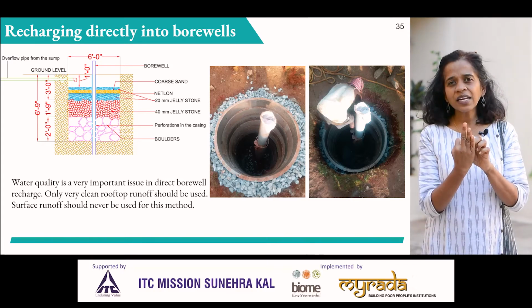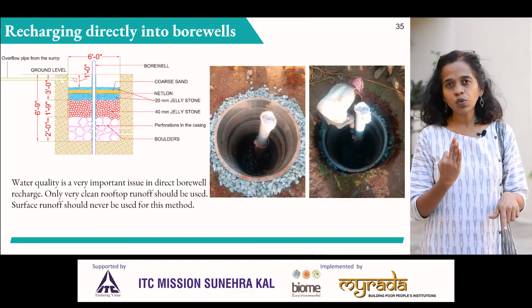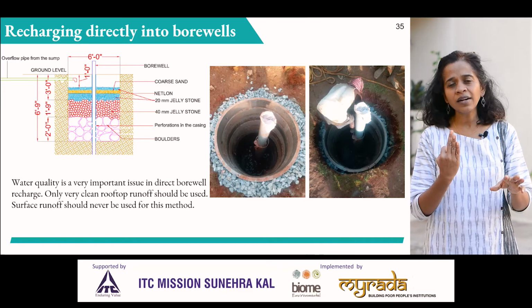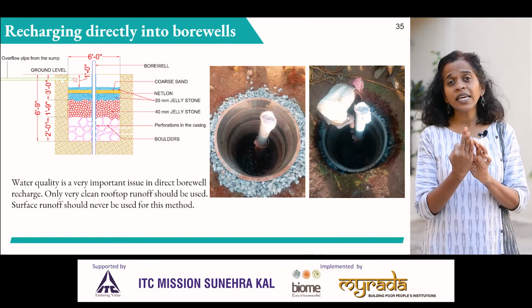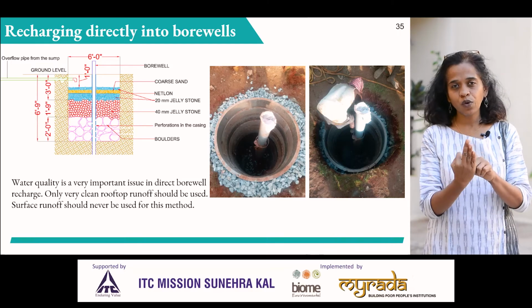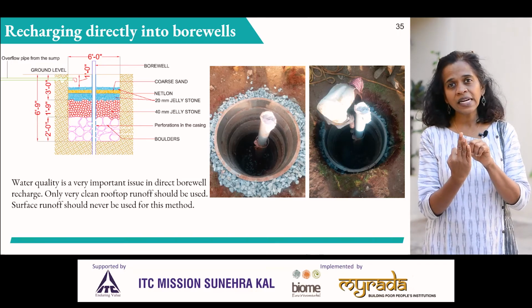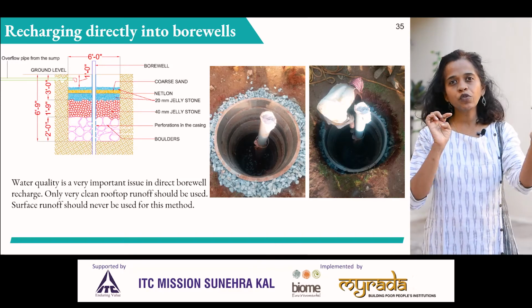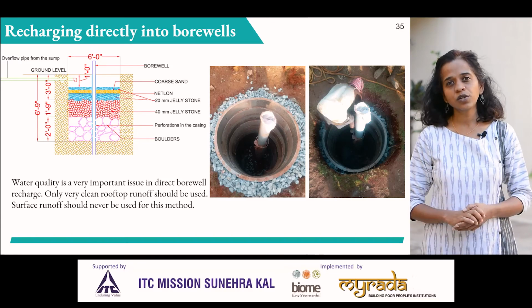We advise that if a borewell is currently yielding, don't try to recharge that borewell, because sometimes it may result in the motor getting some movements, because of which, in case the water source stops, you may blame your rainwater harvesting for it. So it's advisable, if you're doing recharge for a borewell that is currently yielding, don't make perforations in the casing, but just dig a recharge well adjacent to the borewell.